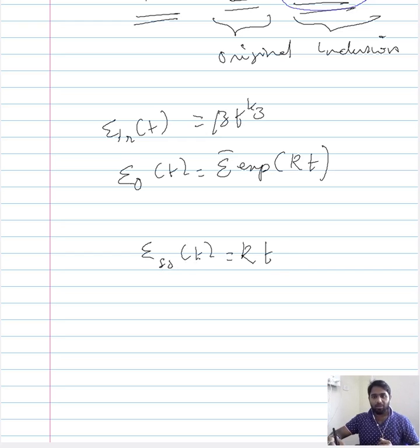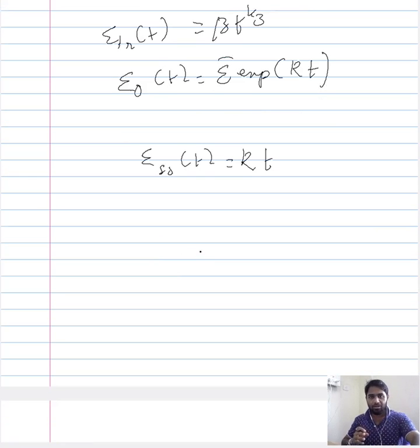So when you consider a time period within the steady state stage, and you multiply it by K, which is nothing but the definite change in the dimension of the material over a particular period of time, then you end up with an expression for the steady state creep, or the amount of strain in that period. So ultimately, now you have your expression for creep over a period of time.